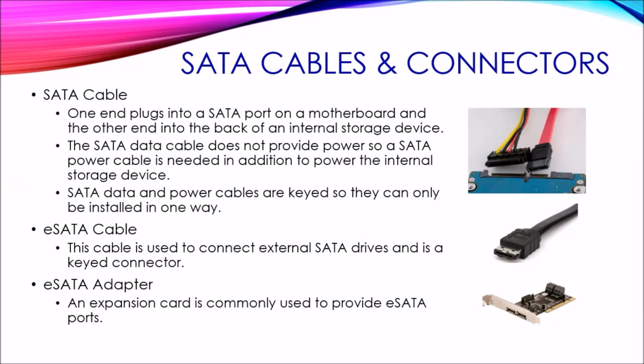The serial ATA data cable does not provide power supply, so a serial ATA power cable is required in addition to provide power supply to the internal storage device. Serial ATA data cable and power cables are keyed, so they can only be installed in one way.